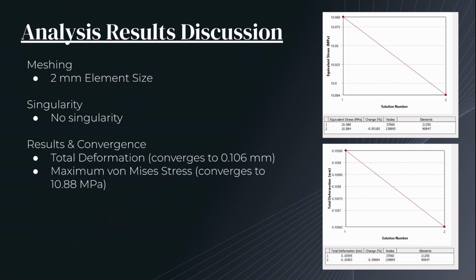We saw that there isn't any singularity, and the total deformation converges to around 0.106 millimeters, and the maximum von Mises stress is around 10.8 megapascals.